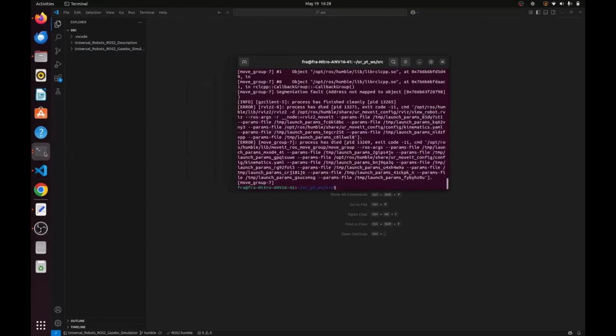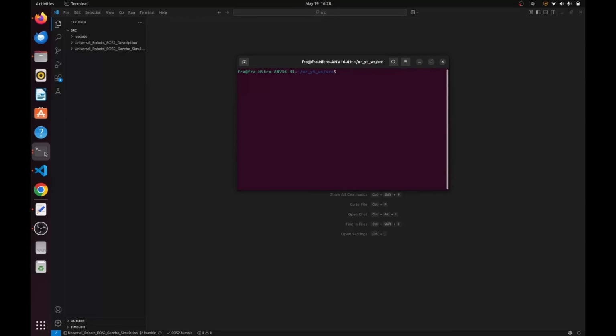So to do that, let's clear this and create another package. So ros2 pkg create. Let's call it universal robots YouTube simulation, sim for abbreviation. Okay, so I'm gonna push this package to a GitHub repository. I'm gonna provide the link in the description down below.